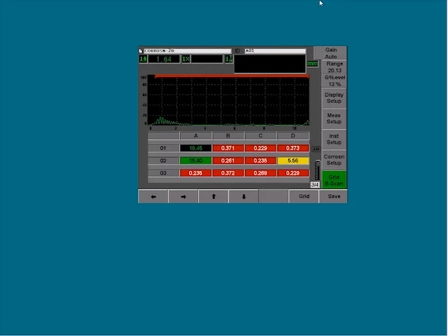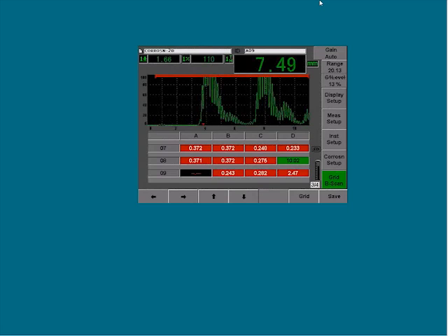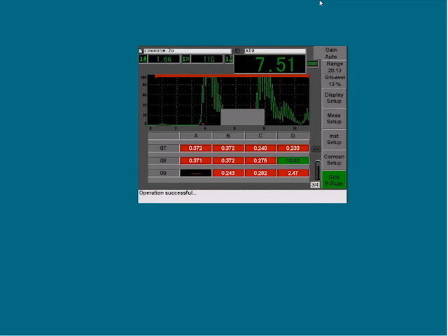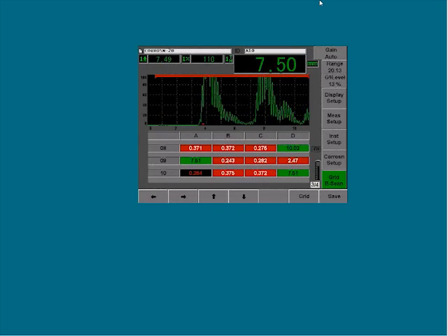But now we can go ahead. On the bottom of the screen here, you see a color-coded representation of a 2D grid file. You have columns A through D, and in this case, rows, I believe, 0, 1 through 10. And we can use these arrow keys on the bottom to explore through our grid file and look at the measurements that have already been collected. And if we get down far enough, we'll find some areas where there's no measurement collected. So I can simply highlight that, couple down to my part, and press the Save key, and it will populate a measurement right there.